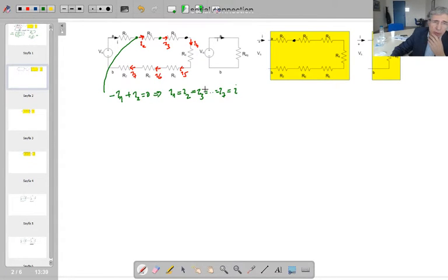So in this second step, our aim is to find what would be the resistor value which replaces these 7 resistors. This current does not change. So we are going to remove all that and put just one resistor. It is called the equivalent resistor value, R equivalent. Then this current doesn't change. So remove that, put this one. So same current. For the voltages, I didn't say anything because you're going to connect this independent voltage source here.